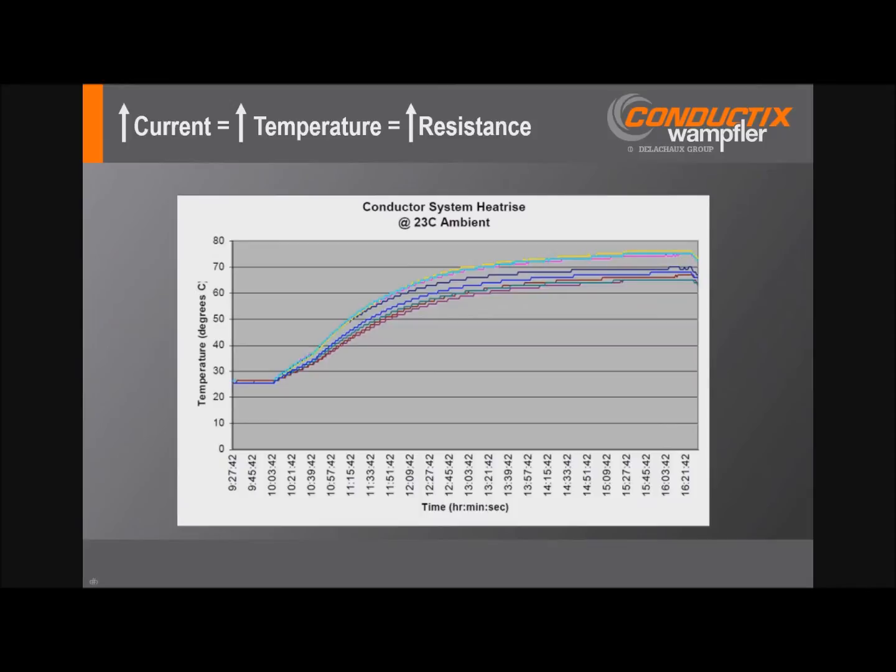Now, power rails are typically described in terms of their maximum steady state current, for example, a 1200 amp conductor. But really for 99% or maybe even more of monorail systems, conductor resistance rather than the current rating really is the primary design criteria. So therefore, the most helpful specification to the power rail supplier is a resistance per unit length. To illustrate, this graph shows how a bit arbitrary the specification of current rating is.